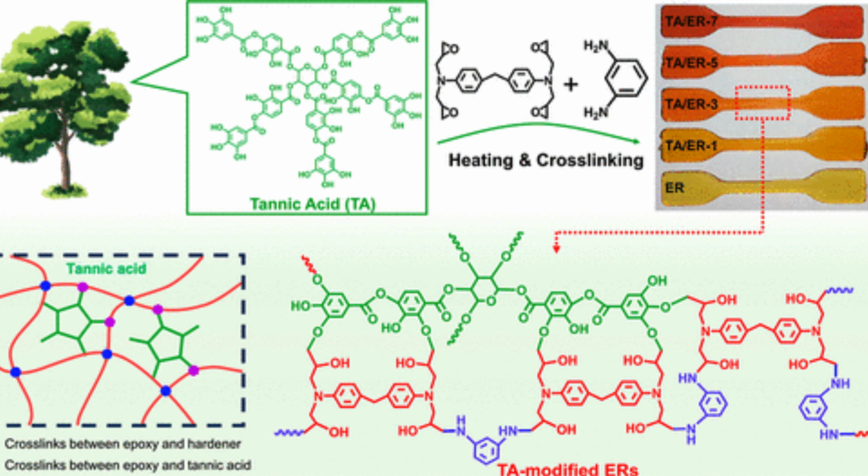The compound contains 4 active hydrogen atoms and reacts stoichiometrically with diglycidyl ether of bisphenol A, DGEBA, epoxy resins at approximately 14.5 parts per 100 resin, phr. Once dissolved in the epoxy resin, the resulting mixture exhibits good handling characteristics and relatively low viscosity.